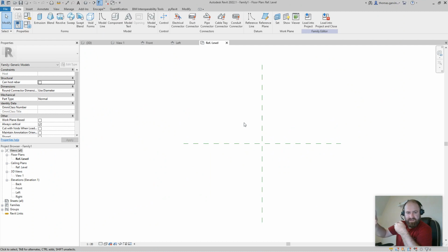Anyway, we're going to calculate the height as ground to soffit, and then we're going to give a soffit depth parameter, a fascia height parameter and a pitch parameter. And then the height we're going to calculate from all those values using some trigonometry. I'll also put the building down below the ground level, down to, let's say, a foundation, because obviously the building might be raised above the ground on your site. I might put a path in as well.